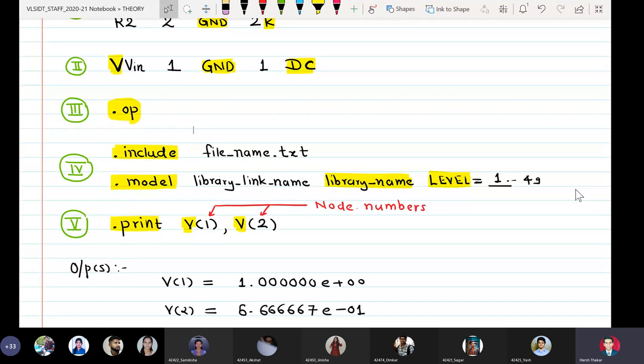For example, if you do the SPICE modeling of an NMOS transistor and plot the IV characteristics, you will see that when the NMOS is in the saturation region, the plot shows the drain current becoming constant, indicating that in the pinch-off region, the MOSFET is acting as a constant current source.